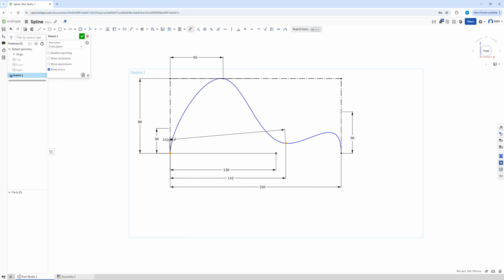And we could make this vertically. It's going to let me go vertically. There we go. Say 12 millimeters. And just to tidy that up, we could bring that over to the left-hand side, like so. You could obviously dimension these points from anywhere. So we could dimension it from the origin, we could dimension it from a top corner, whatever you want to do. Quite useful, very good little tool.